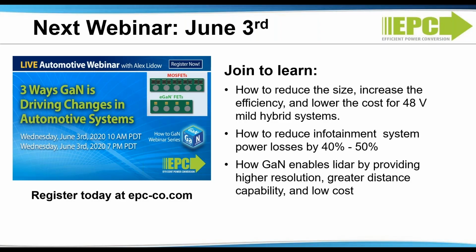With GaN, the entire power loop is usually under 250 picohenries. And remember, the package alone in a MOSFET is 1 nanohenry. So we have much lower overshoot. An easy comparison: it's about 70% overshoot in a MOSFET design versus about 20 to 30% in a GaN design if you do a good layout.